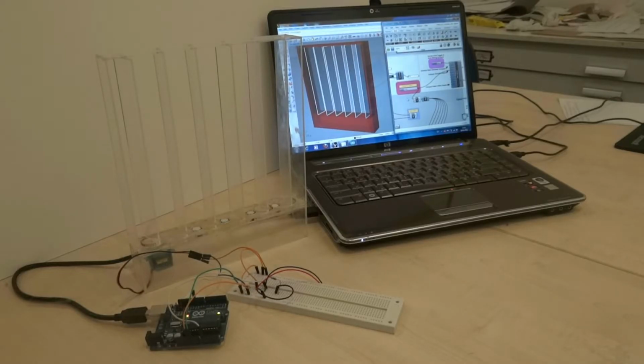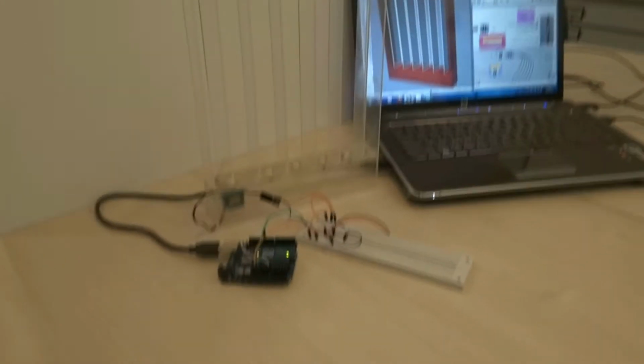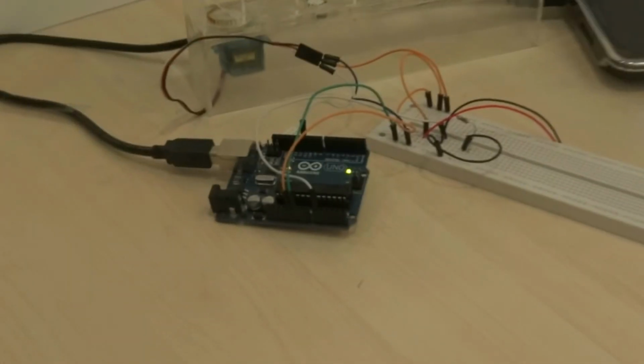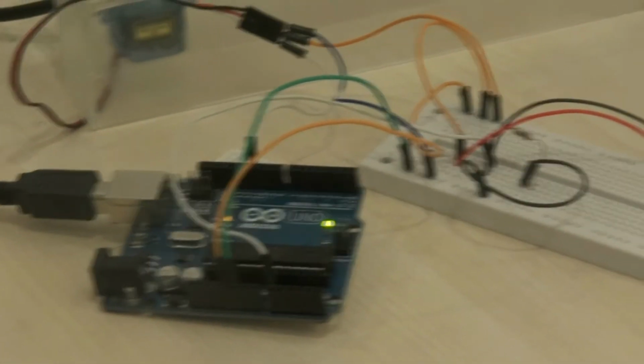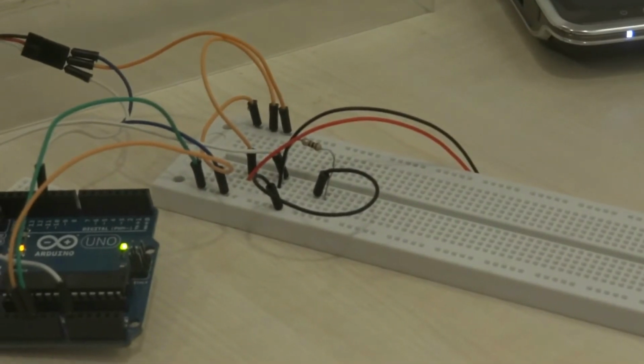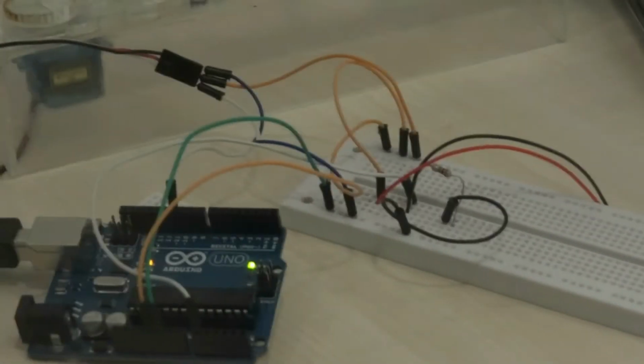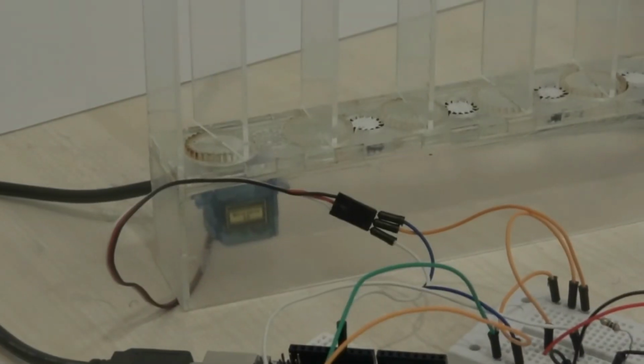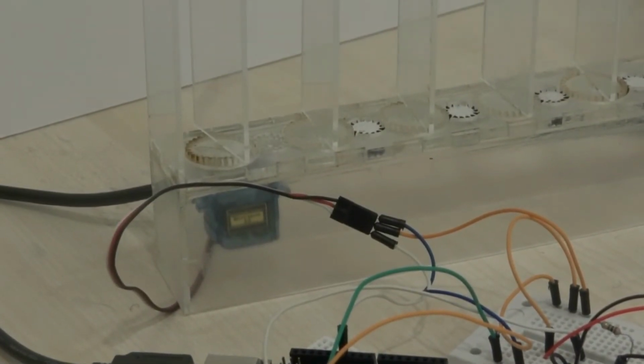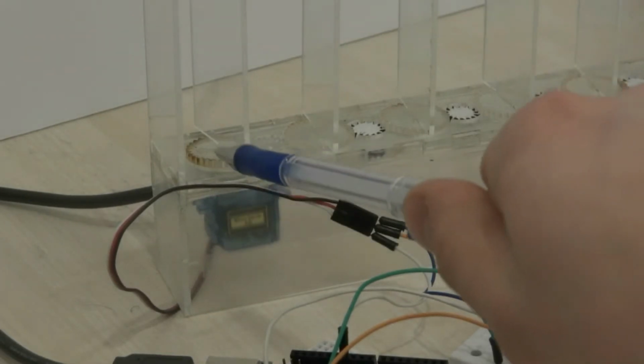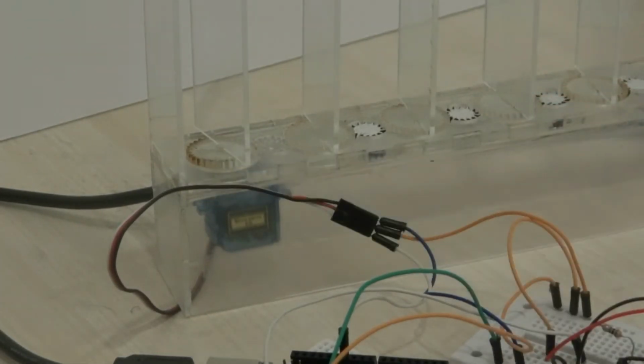So here is the setup for the project. I have the physical model, which is connected to this Arduino Uno board, which is the open source hardware program, which is also connected to this breadboard and the laptop, and this controls the physical model, as I've already shown. The physical model has one micro servo, which is attached to this gear and these gears here, which control the 6 panels which are designed to open and close according to the wind speed to protect the inner of the 2 skins on the Dubai Ambient Tower in high-speed dusty winds.